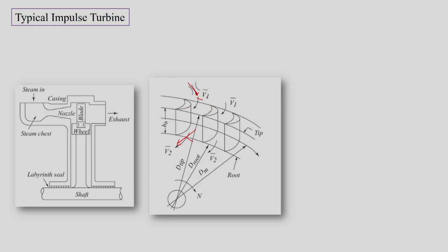In the case of an impulse turbine, the flow will directly hit the blades, and due to this interaction of the steam and the blade, the blade will try to rotate. Here we expect that while flowing through the passage of the blade, there is no enthalpy drop and no pressure drop for the blades. Here we are actually seeing a rotor ring in our slide.